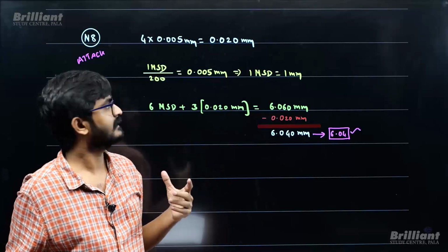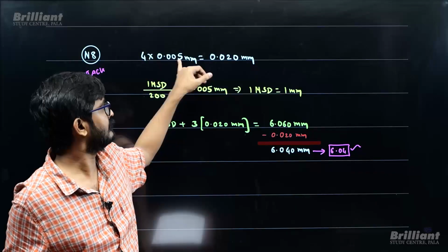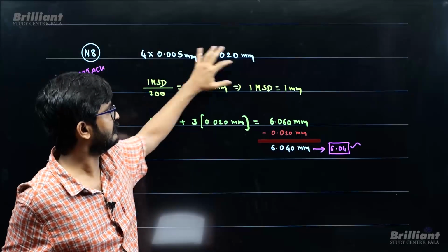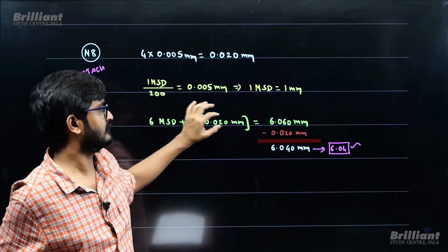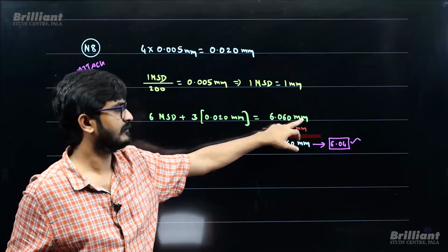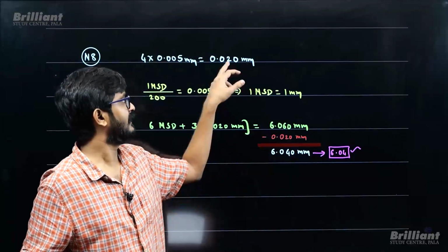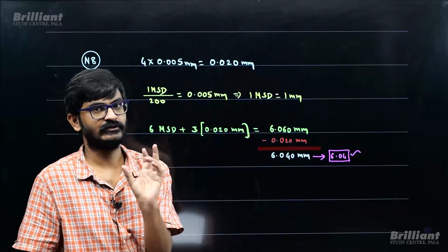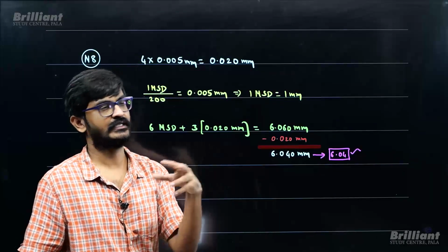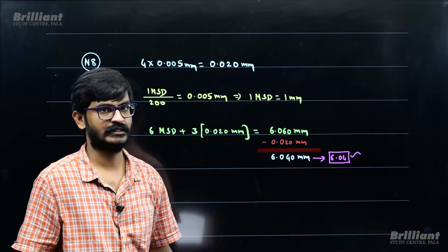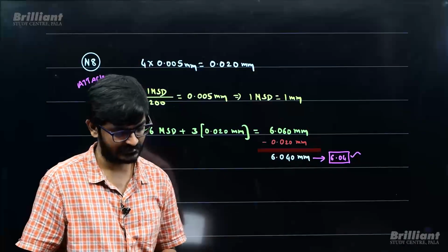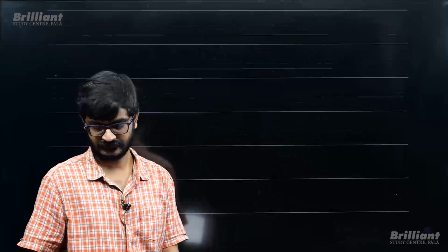Plus what they said, it is showing 12 times the least count, or 3 times the initial value, extra. So this is because of main scale reading, and this is because of circular scale reading. But what is the problem? The problem is, earlier we saw when the length is 0, it is showing extra. So if we want to find the actual length, we need to subtract this much. Then we will get the actual length. So what is the length we measure? That is the diameter, right?